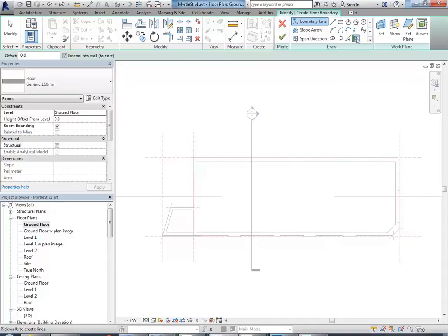Now, sometimes when you press tab, it won't detect what's under your cursor because it thinks you're in a number field or something. And so there, notice it's not tabbing properly. So another tip I can give you there, just click into an empty space to make it realise you're in the drawing area, and then tab should work. So there it is. Tab's just your option key, and there we can get it to chain if I do it in 2 steps, just to save a bit of time.